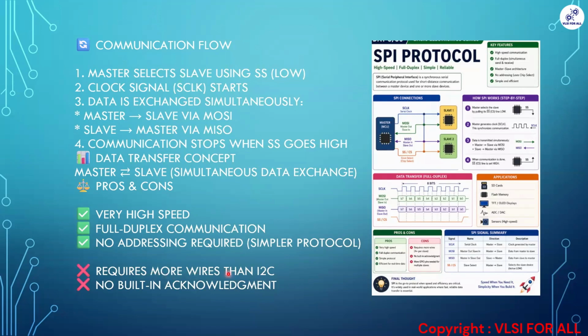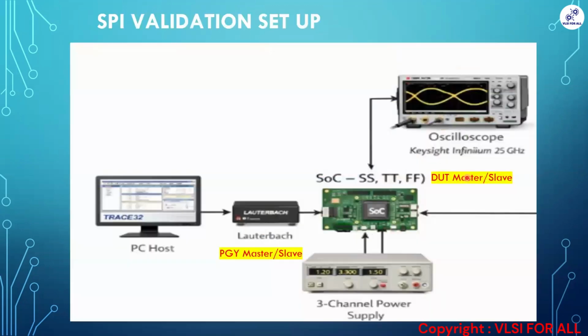Coming to the disadvantages, it requires more wires than I2C, and there is no built-in acknowledgement. The acknowledgement bit won't be there here, and you can see visually through this image how it will look and how the communication will be there.